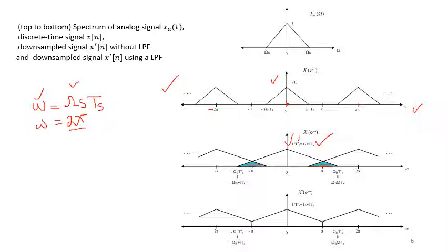Now to overcome this problem, we propose a low pass filter, right? So as from the discussion on the previous slide, I hope this gives you an idea. Once we low pass filter it, we can remove these regions. So now you can see there is no overlap, right? Because of this overlap there would be distortion, that is called aliasing distortion.